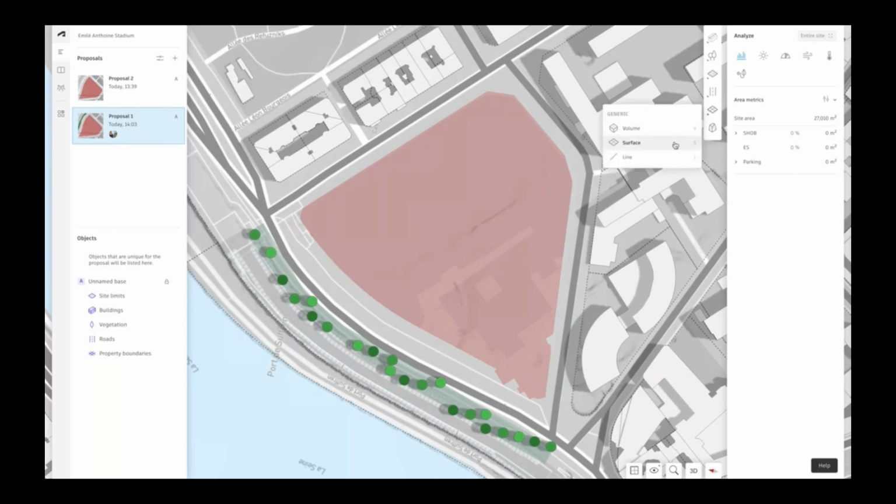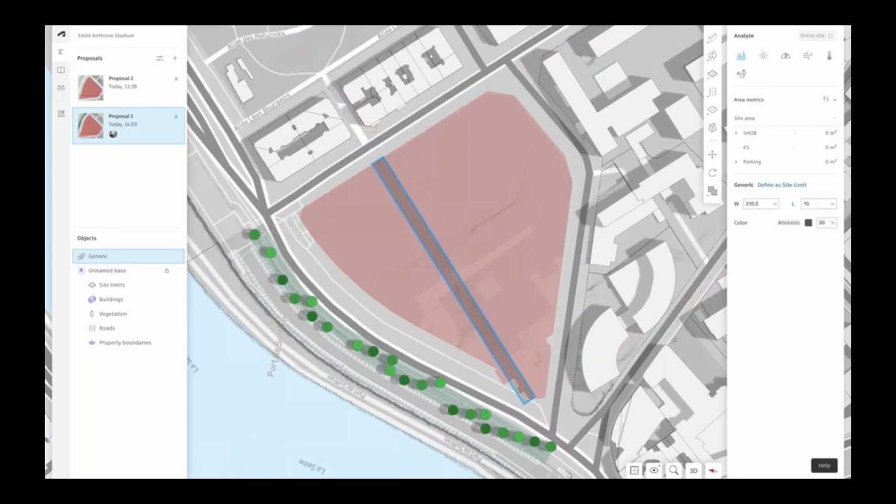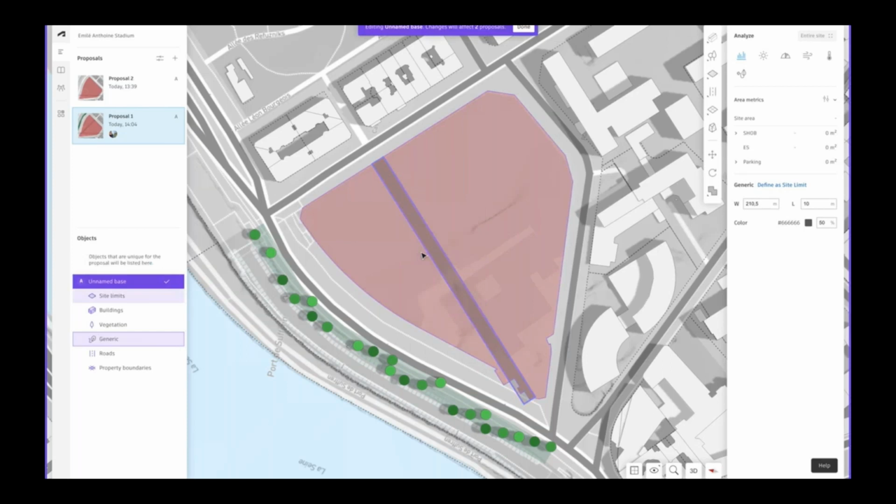as per our requirement. Considering that I'm creating the surfaces into divided zones, I'm creating a passage with that size limitation. What sizes I want to give, I can directly key in the values in the interface. Once you have completed the sketch, it automatically creates the shapes, and based on that, you can add or subtract. Currently I want to divide these zones, so let me just subtract this region from that. I'm moving that to the base layer, and I'm trying to delete that.